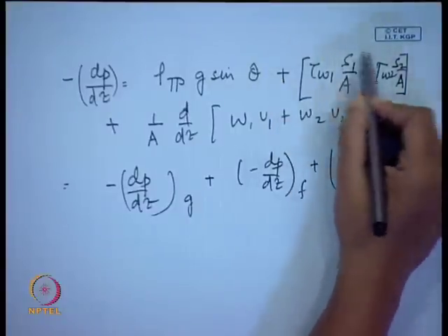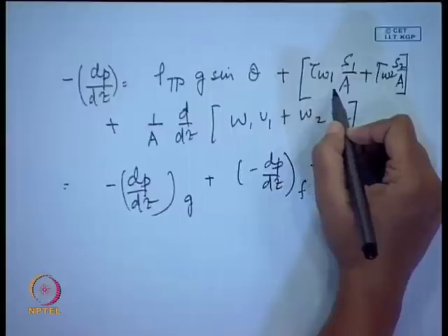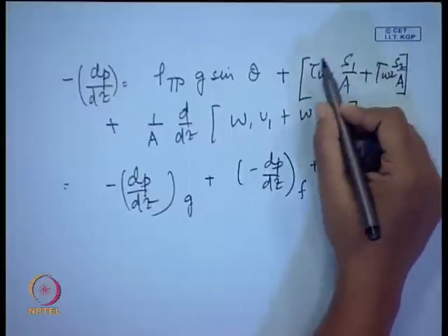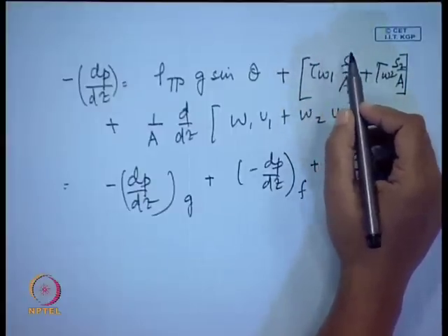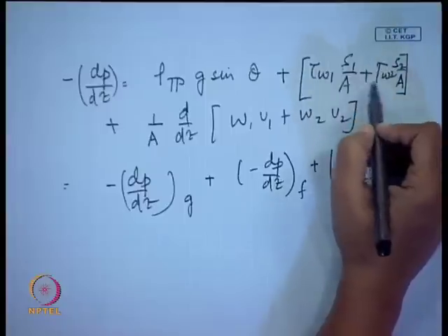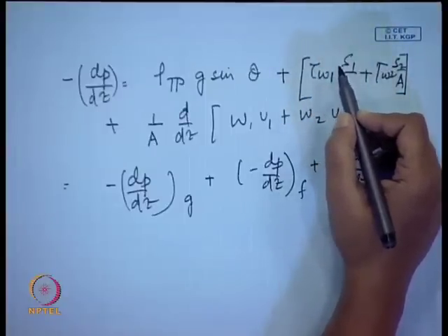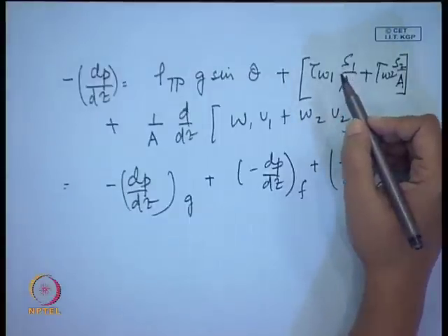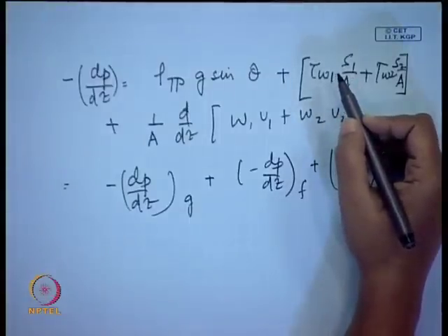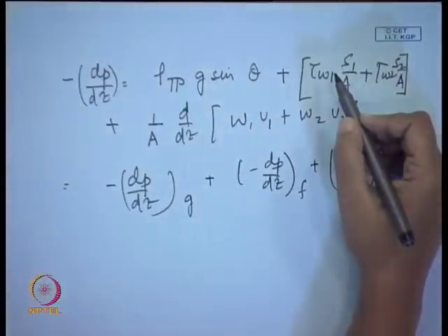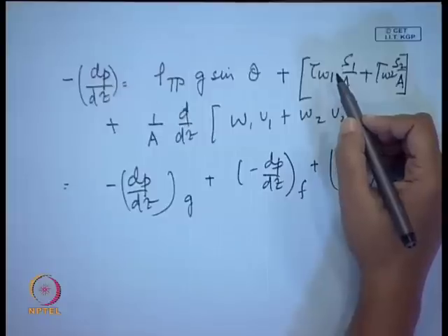Just like in homogeneous flow theory, we found there it was just tau W two-phase, isn't it, S by A. So for tau W two-phase we had devised several techniques to find tau W TP based on our knowledge of single phase flow. Either we had defined an F TP based on a Reynolds number TP, which is again based on a mu TP and a rho TP, okay.